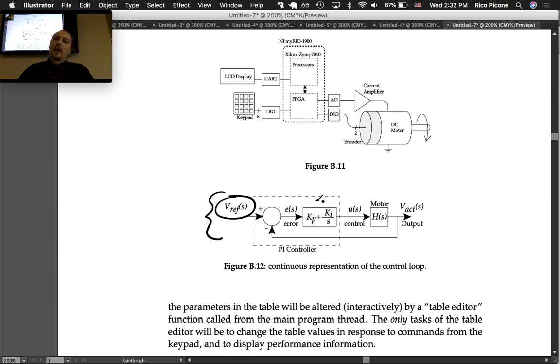A proportional term, which is proportional to the error. So if your error is 1 radian per second, then it's going to be 1 times whatever your proportional gain is of actuation to the motor to try to make it happen. So the further away, the larger your error is, you have some proportional response from the controller.